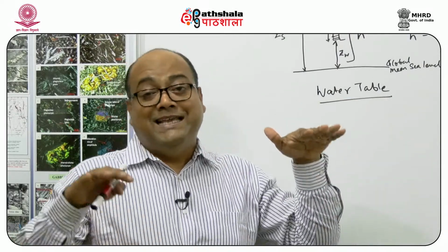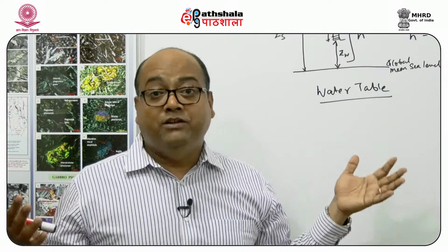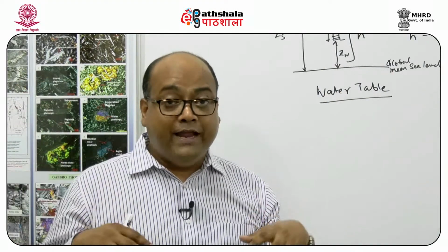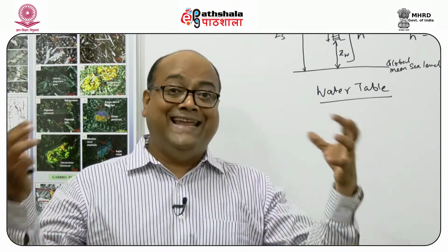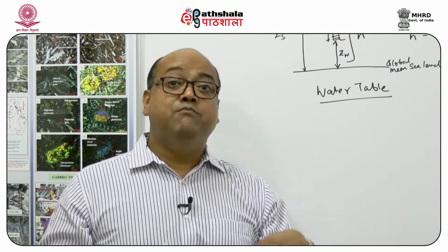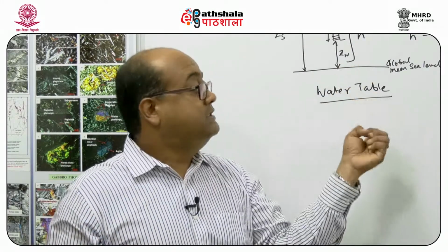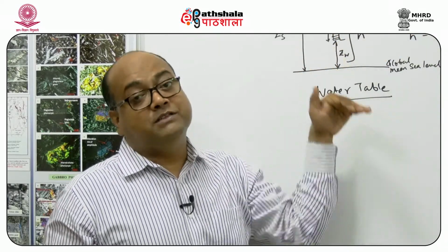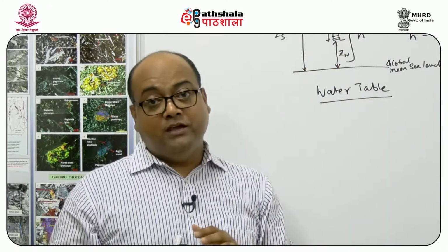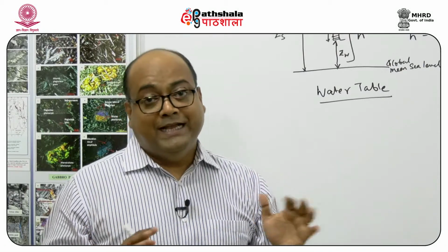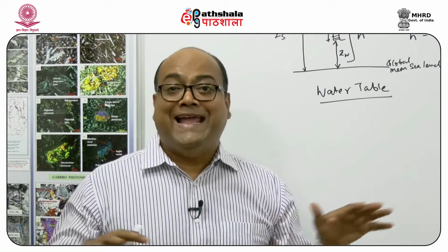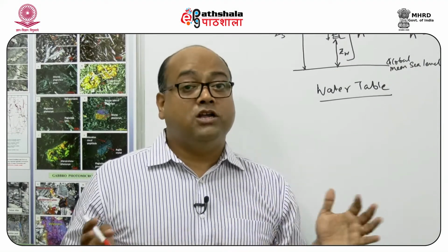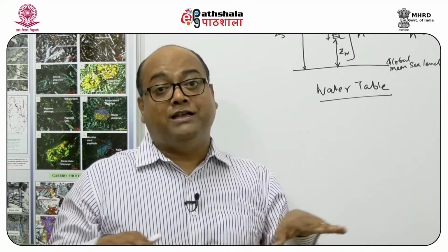During the monsoons, when there is a lot of rainfall, the input into the system is more than the output, that means more than the groundwater that is extracted out of the system. Then the water table rises. So here the water table defines the hydraulic head of the area in very simplistic terms, and it is not a constant surface. That means it is not time invariant, it varies in time.